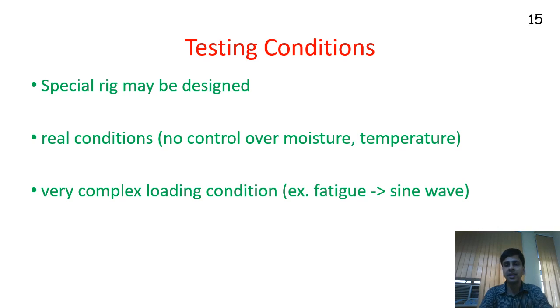So typically when you are testing a real structure, it is to replace an existing structure, and the data of the loading is available for that existing structure, and you have to replicate the exact same loading in the part that you have designed to prove that your new material, your new design is actually working.